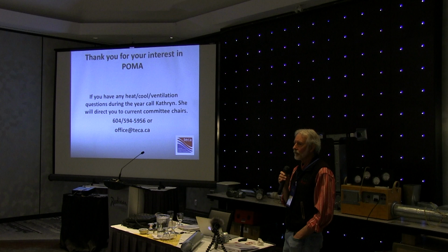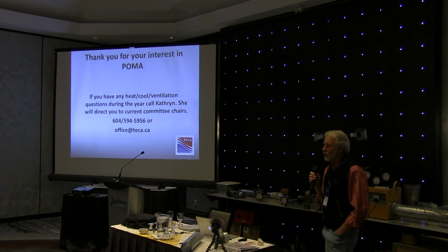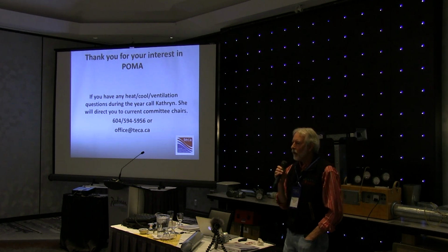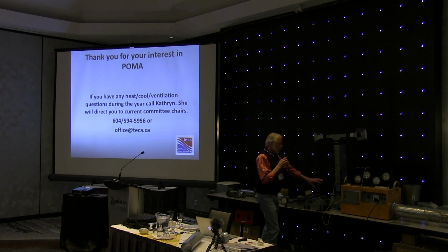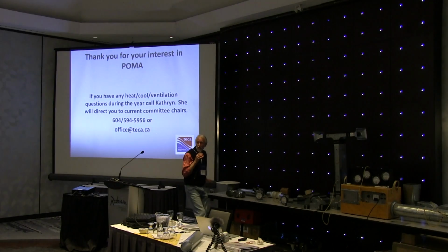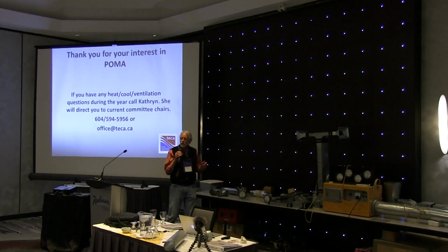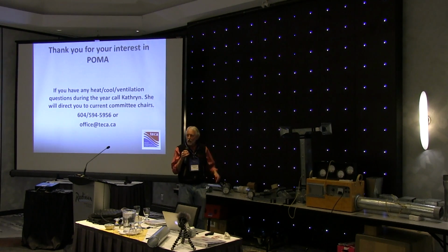With regard to your comments about measuring the return area and the supply or cross sections, are they supposed to be equal? No. I'm sure they don't have to be. When I look at a fan, this fan is better because this is ducted on the return and the supply. I could not answer your question looking at the bath fan. This fan does not care if it pushes hard or pulls hard. It sees the sum of the two works.